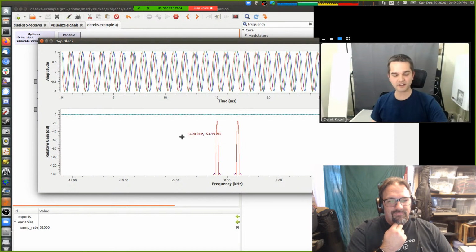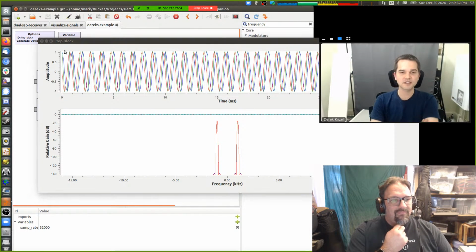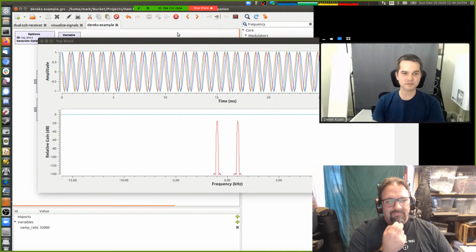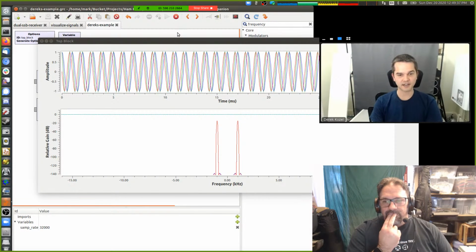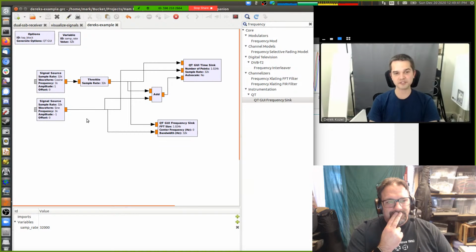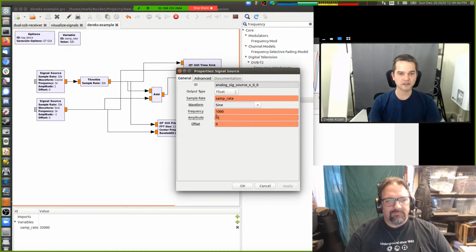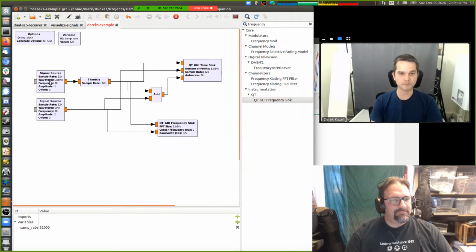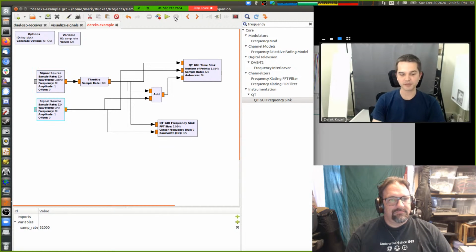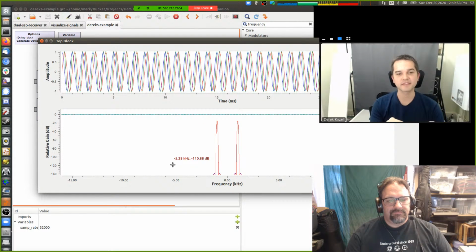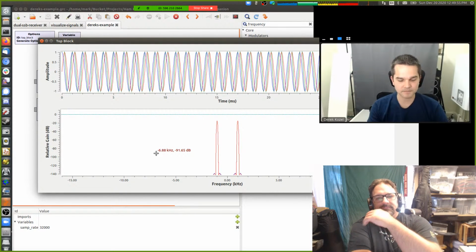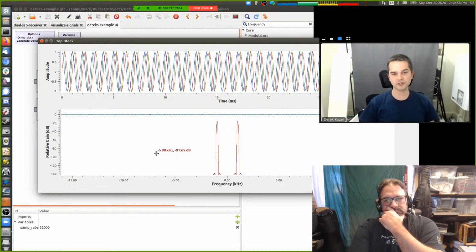But there's a property of real valued signals that they are symmetrical across the frequency domain. So you get a negative frequency for these sine waves. And that doesn't matter at all when you're talking just audio, because your inputs are all positive frequencies. But one of the things I came to realize is that it's really useful to realize that this is just part of how the math works out.